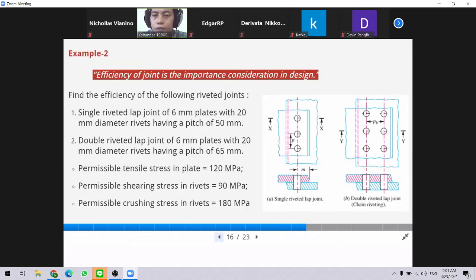So using this geometry, we know that this double rivet can increase the efficiency, but it requires larger overlap area. It becomes very dense compared to the first type of joint, and because it has more rivets, it requires more manufacturing effort.